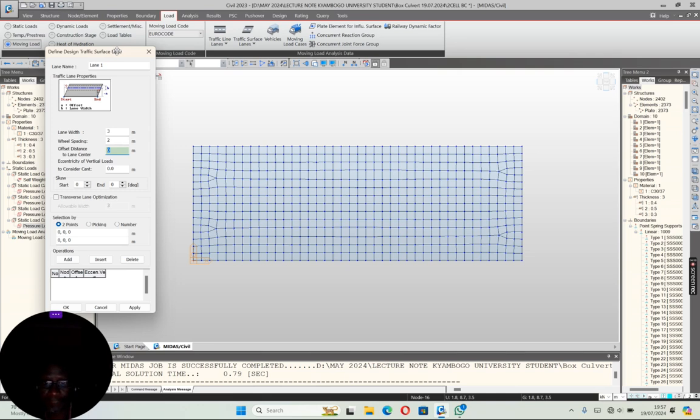So I'm going to come here and indicate. I told you that the offset to the center line is 1.5 because I'm at the boundary of the two lanes. You have the 3.5 to the left and 2 meters, then the 3.5 to the right and 2 meters. So that gives you 5.5 and 5.5. If you do the national lane as per Eurocode norms, then it is 3, and the next would be 3. But because I have a remaining 2.5, that becomes 1 lane and a remaining 2.5. So now I have my offset at 1.5.